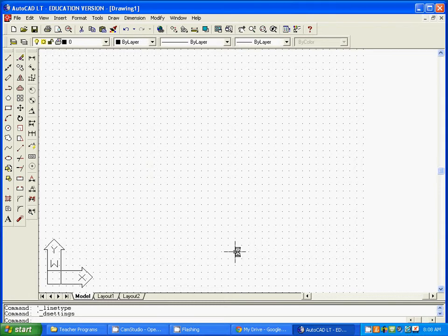The drawing we're going to do for this tutorial will be number 6 from your isometric drawing sheet, and it is the drawing that has the rectangular block with the rectangular opening in it. First thing we need to do is make our front view. So I come up here, select line, and I'm going to go right about in this corner here. And I need to look down at my sheet and determine how tall the front view is going to be. Well, we know by looking at the picture and counting up the squares, or looking at the dimension line to the right of it, we know that it's 4. So I'm going to click, and I'm going to go up 4.